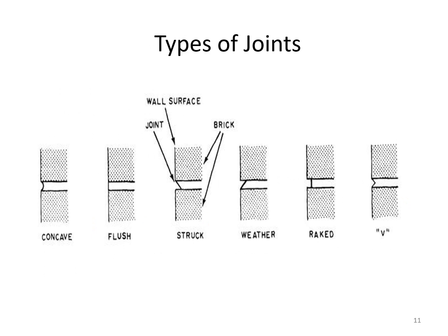You see the concave one. That's where you've passed that second tool. It looks like a half-rounded piece of metal. It could even be done with a round tube, let's say, that would give the same effect. The flush type is just when you've cleared with that triangular trowel, just cleared the face of the brick straight. You have this other type called the struck type, where it's turned back at a 45-degree angle.